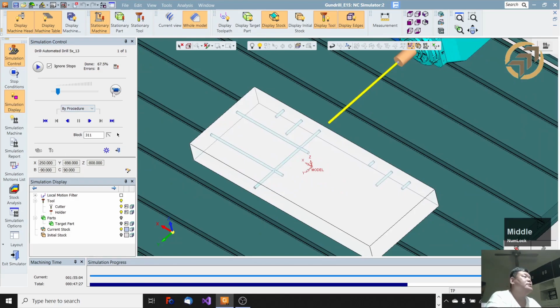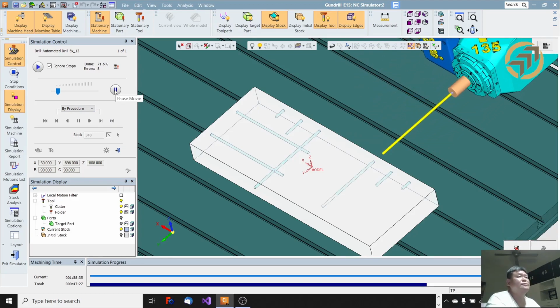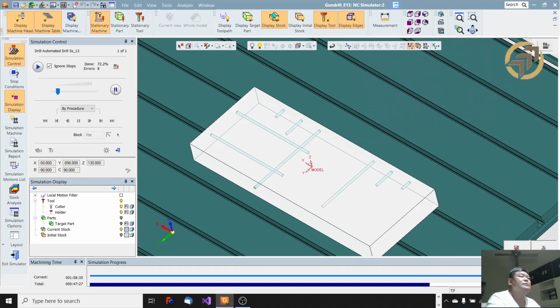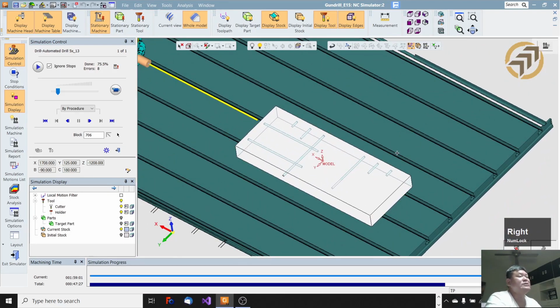Okay. So the next hole is the same. There's no cross hole, right? So you can say by using the 400 mm is not enough. So the system will add another cutter. The next cutter will use an 800 mm gun drill, but the diameter is 9.95.